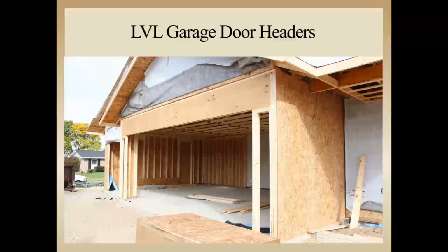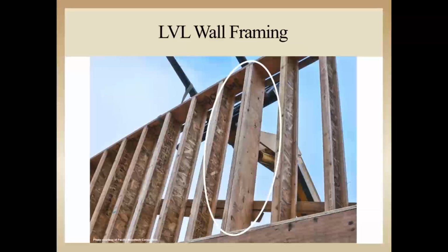Now in this photo, LVL is being used as a column in an I-joist studded wall system. I-joists are not typically used as framing members in walls, but are used this way in some very high efficiency passive energy home designs.